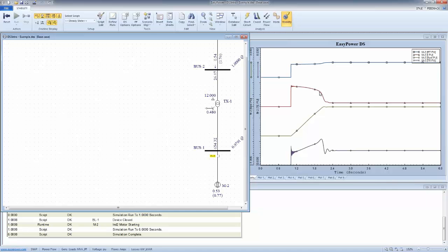Let me just mention faults, different transient faults, motor starting, governor and exciter tests, load shedding, load additions, any other type of transients, including, let's say, faults that trip a breaker. Meaning that you have a fault, but you don't open a breaker. You let the system decide if the breaker opens. All those transients can be captured in the dynamic stability module.